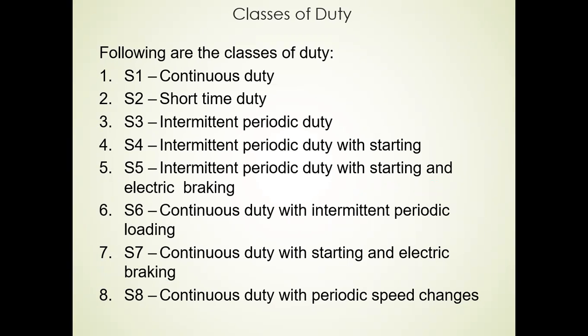Here, the temperature rise depends upon the operating duty for a particular machine and depends upon the local conditions of load and duty cycle. Precise operating duty varies with various operating conditions, and the standard duty classes are for the guidance of the manufacturer and also the user. So some standard duty cycles for industrial rotating machines are described here.